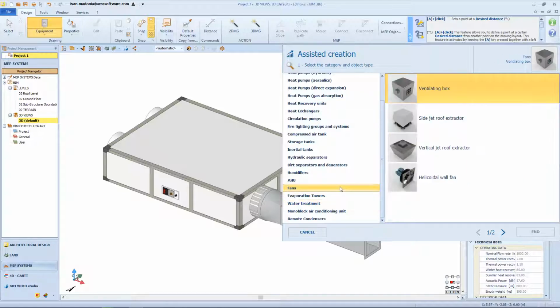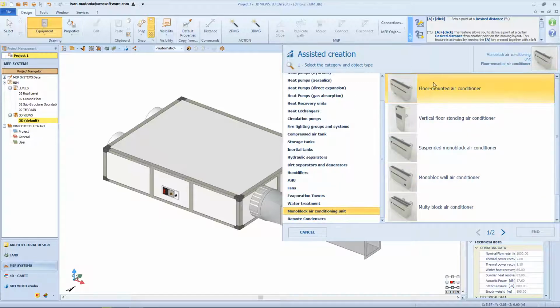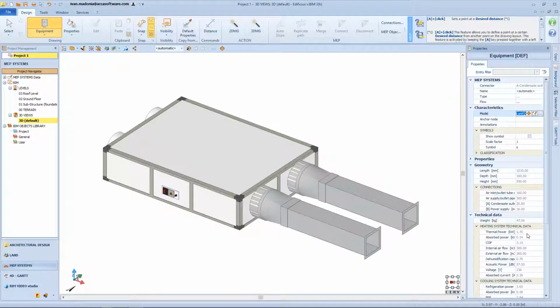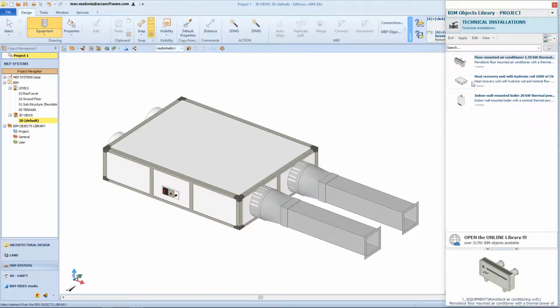The profiles in the project library are updated only when the entity is selected from the drawing menu, even if it's not then inserted on the model or in the case in which, after being added, it's deleted. Therefore, the project library dynamically follows the choices made during the modeling phase of the MEP entities, progressively updating itself with the selections made and the settings foreseen for the relative parameters. From the drop-down menu you can choose to select the item from its category in the General Library or from the User Library.